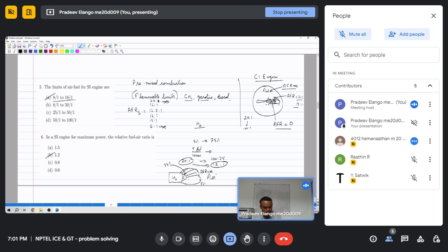So beyond this it is fully flammable, whereas in case of LPG it will be similar to gasoline, say 8 to 18. So then the flammability of LPG, if it leaks somewhere, only a small region will be flammable, and once it is mixed well in the air, it is not flammable. But here for hydrogen, a large region will be flammable. So that is why hydrogen is more difficult to handle.